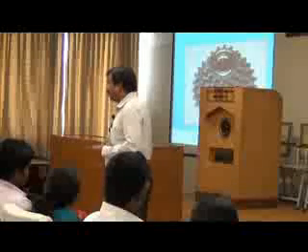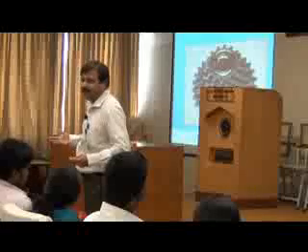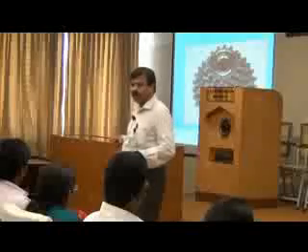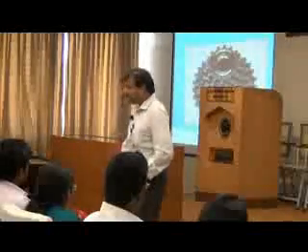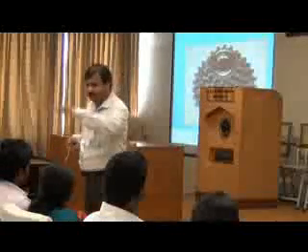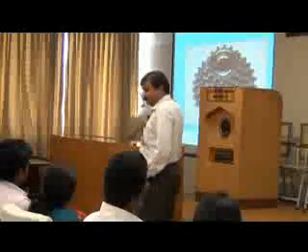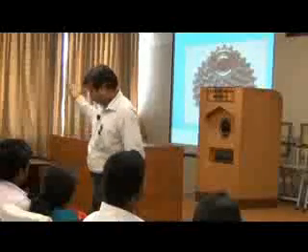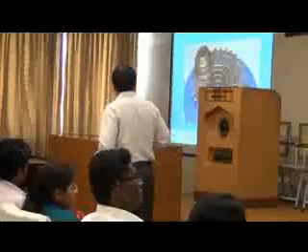Initially when starting, inertia is a big issue and I have to overcome that. So you start with high torque, low speed, and then after attaining a particular speed, you can change. This is the basic idea behind gears, be it in a bicycle or a two-wheeler, four-wheeler, everywhere.